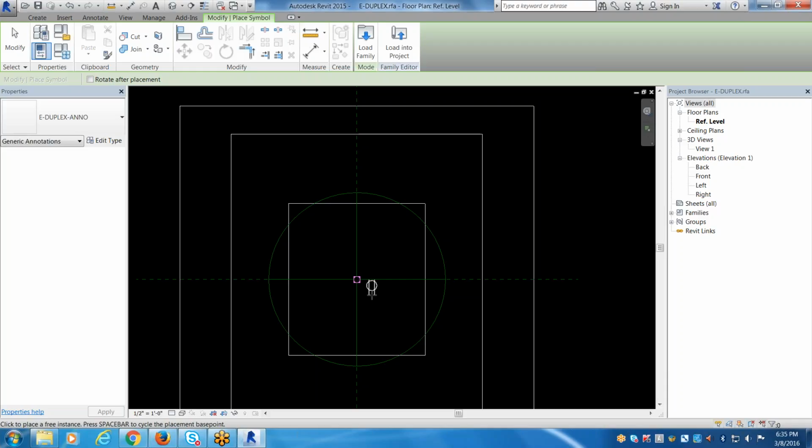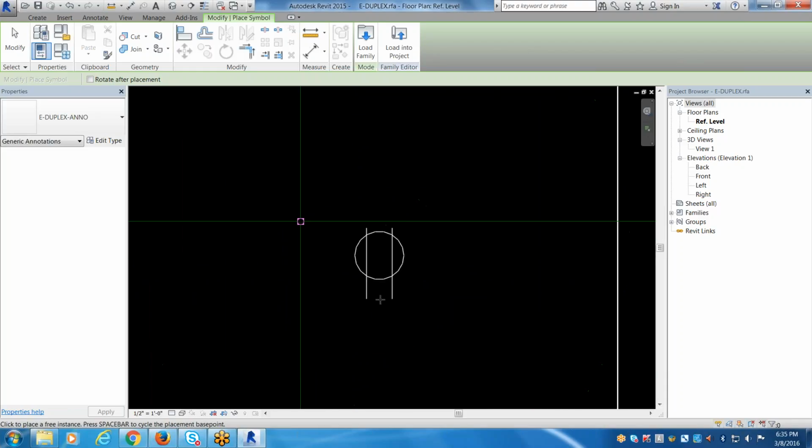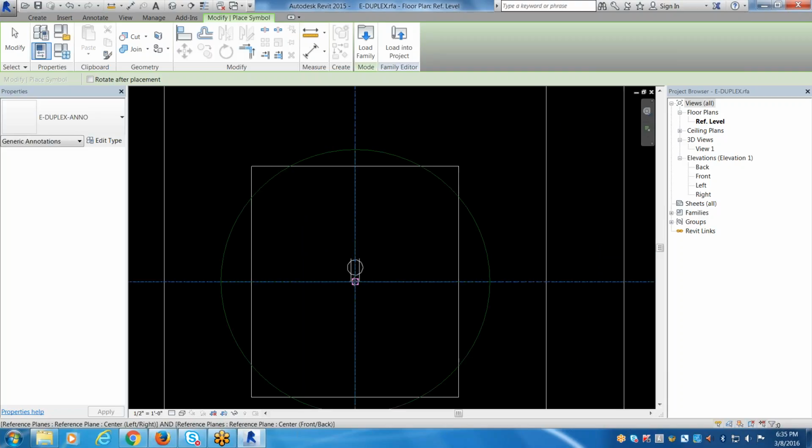Like it's that paper, it's already annotative. When we create annotation stuff in AutoCAD, it's a little more weird. This is just straight up, what size on the page, that's it. Really slick. And you'll notice, where is my insertion point? Right in the middle of that thing, because that's where we placed it when we created it. This is where we want that insertion point. We don't want it here, here, here. Perfect. And now we're going to place this right here, dead center.